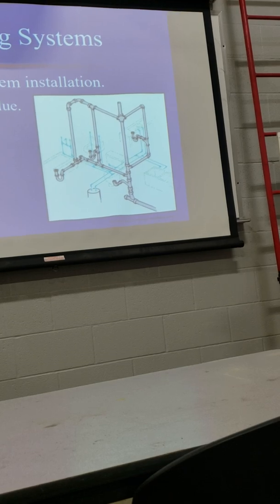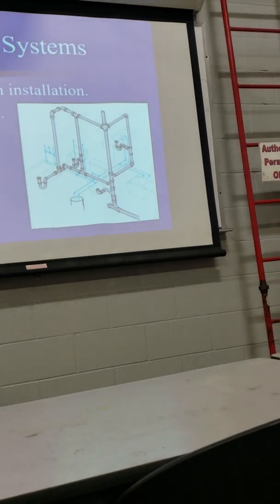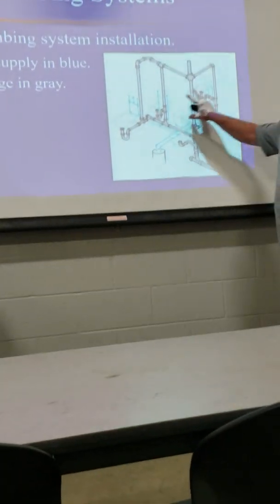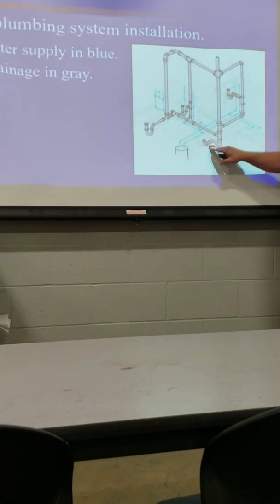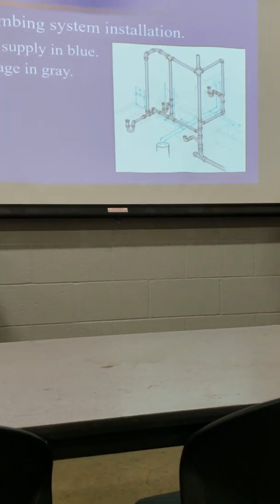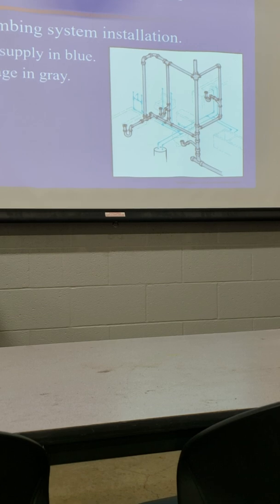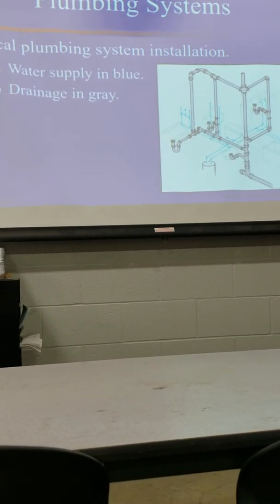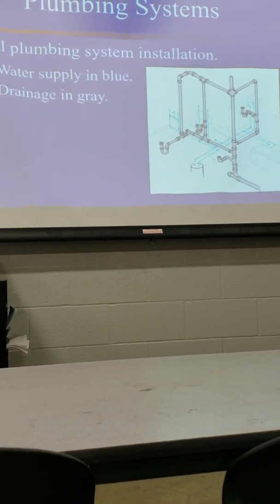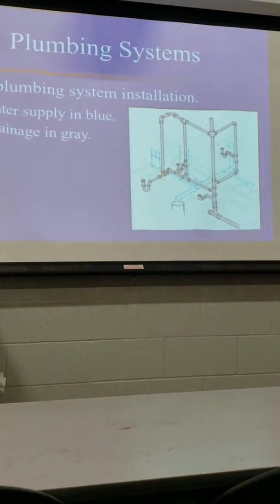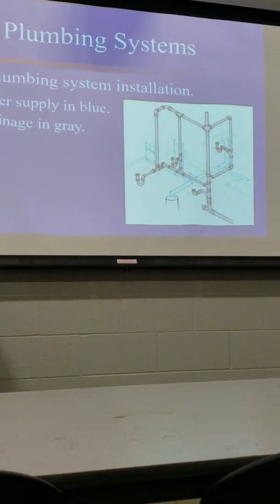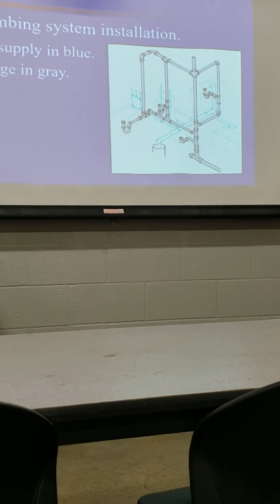The reason that Kentucky doesn't like it is we get all those dumping at the same time, it can pull water out of that water closet, alright? Create its own vacuum. Right, so that water in the water closet and the water in all our traps is our water seal.